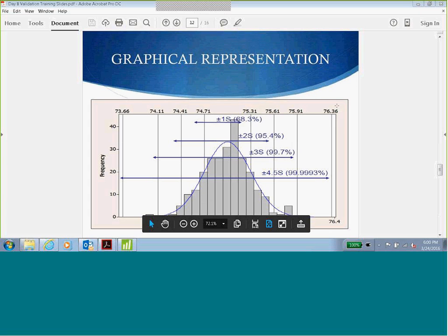So you will have the specification limit, and you will be plotting this graph based on your sample mean, and you will be calculating the standard deviation, and you will be plotting plus or minus 3, so plus 3 and minus 3. With respect to that, you want to have all your samples within that plus or minus 3 standard deviations. That is the industry standard, as I mentioned.